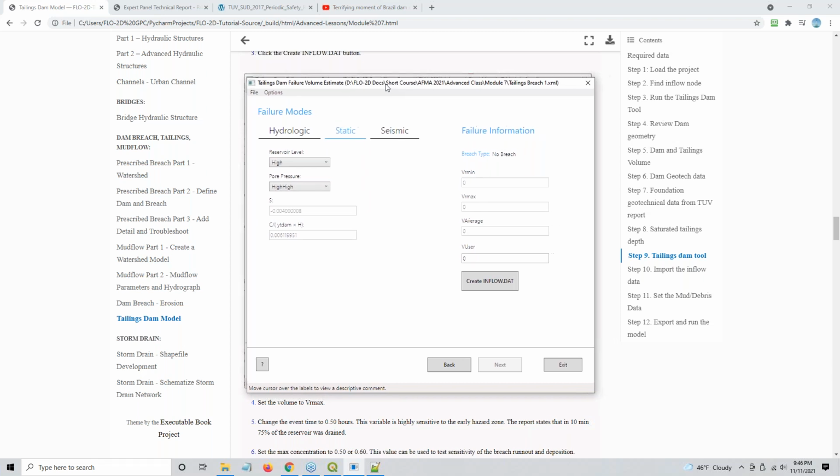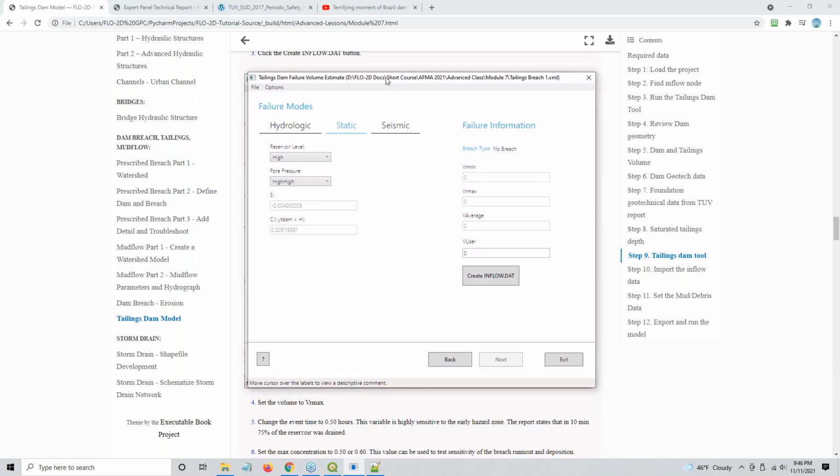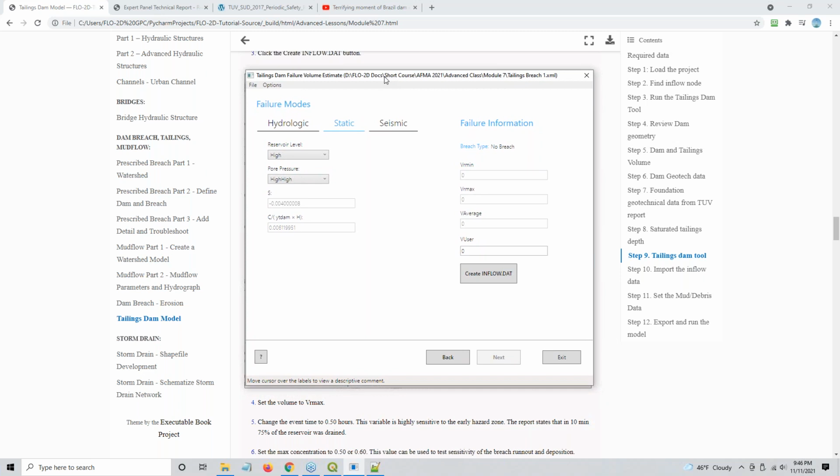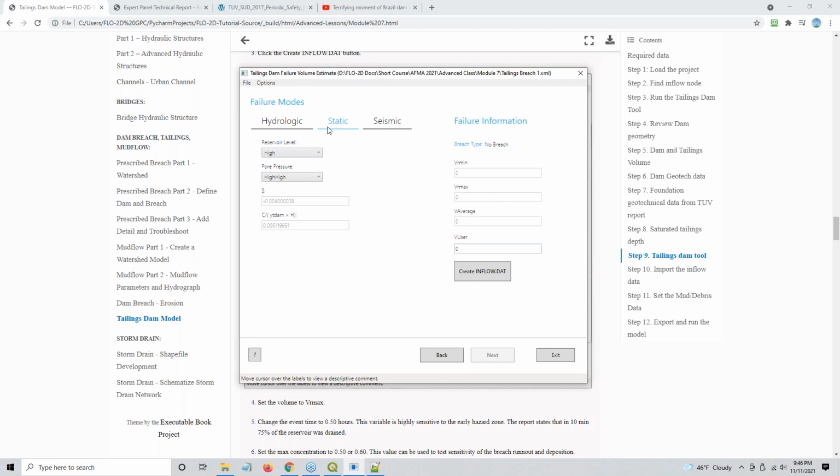So this is an iron mine. So this is milled iron tailings. So the particulate size will be low, but it doesn't necessarily have to have a lot of cohesive soil in it. It could be pretty sandy soil, I think is what they say in the report. And so the liquefaction of it is based off of finely milled sand particles. And so if you have a high reservoir level, it won't fail.